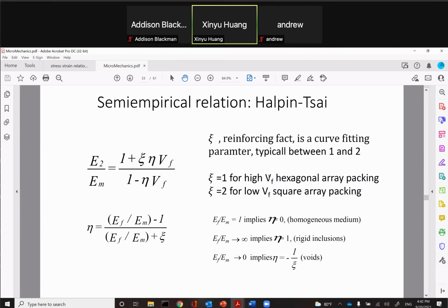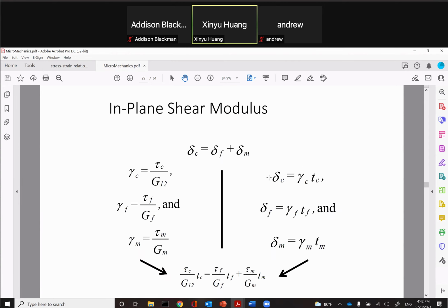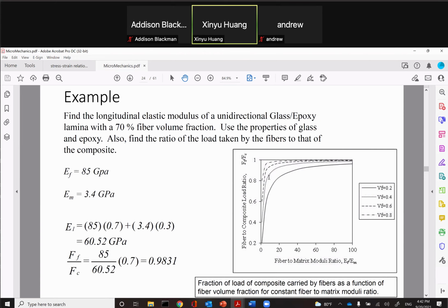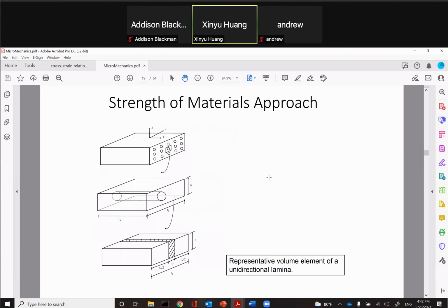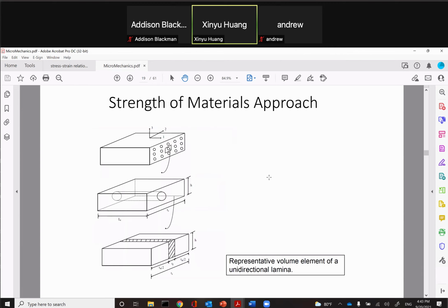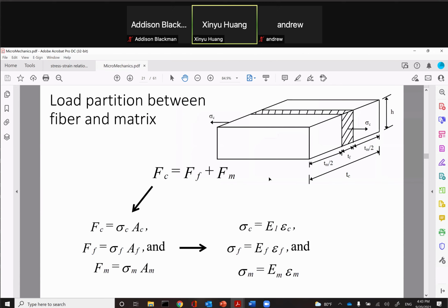All right, so we're basically looking at micromechanics approaches. We talk about two approaches, really. You look at all the approaches available. We basically look at the mechanics of materials approach. You introduce some highly simplifying assumptions, you apply solid models, and you can come up with a model. Usually, it's one form of the rule of mixtures or the other. Okay, that's the most basic form.